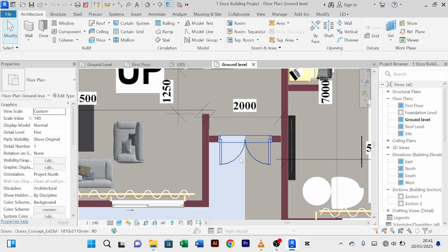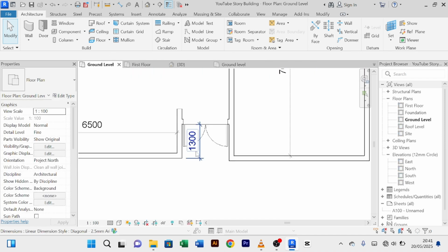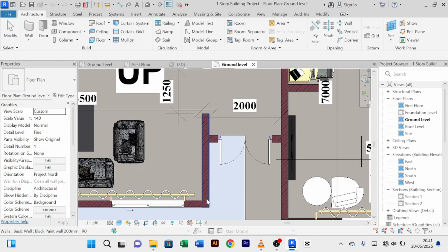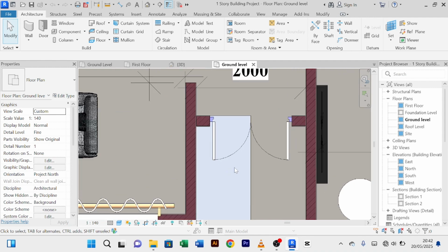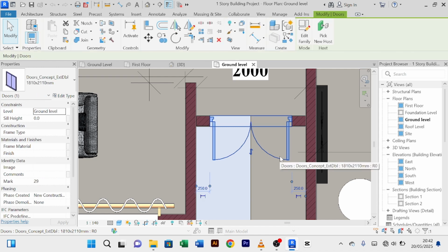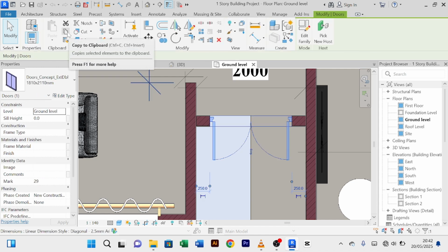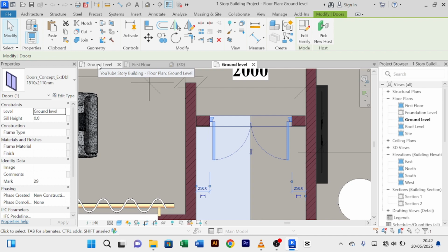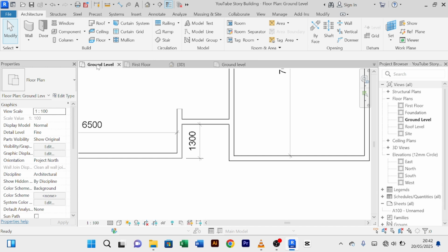We are going to use these doors instead of this one here. I really don't like this at all. So for me, what I'll do, and the same can also apply to you, if you have a project that has all these components, you open the project in Revit, you click on the component you want to copy, then you come to this tab that says copy to clipboard, you copy it, then you go to the level where you want to paste it.